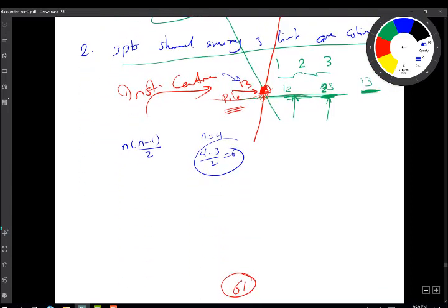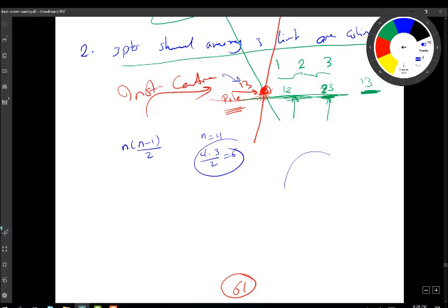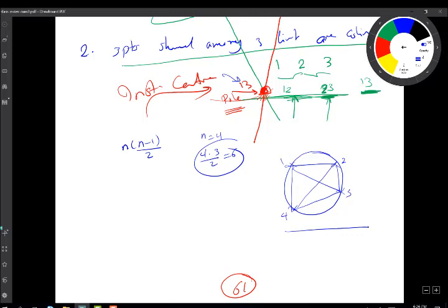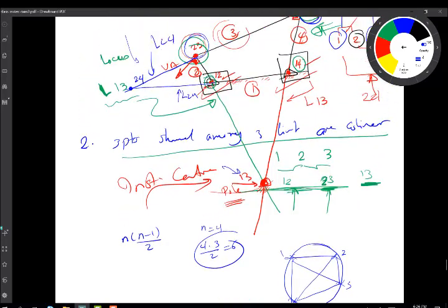In some textbooks they draw a circle on the side and put points like numbered links, where every point represents one link, and they connect them, making sure every two points are connected. When every two points are connected, they know they have got all the points of common velocity in the linkage. That's one way of working in a systematic fashion.